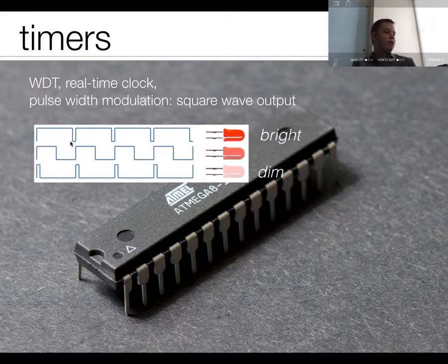high, digital logic low, digital logic high, digital logic low, high, low, right there, okay? And its job is to generate a pulse width. So it's going to generate pulses. Let's say you're running at 100 hertz or something. If it's high for a very short amount of time, that's called a small duty cycle square wave.